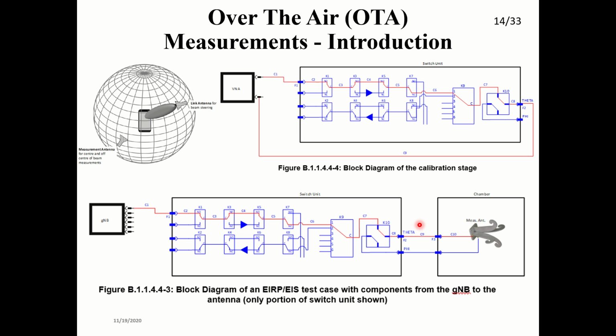That time what happens is, for example, you are getting some 10 dB of gain, for example 10 dBm power plus 10 dBm power. But actually you should get 15 dBm power plus 15 dBm power. Why? Because you are not compensating this path. For example, this path is offering 5 dB loss, so that we have to find out in the calibration stage.